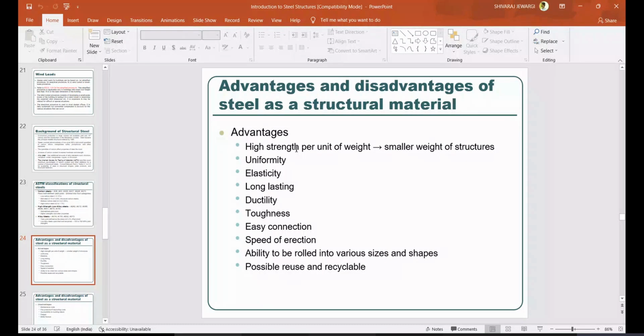Do you know, in the RCC class we have discussed, if you do not use any rebar or reinforcement in a concrete structure, what happens if load is applied on a particular member? Since it is made up of only concrete, it is brittle in nature, since concrete is good at compression. If that member is subjected to tensile stresses, the material is not able to withstand them, so suddenly it will collapse. In order to prevent that, the reinforcement or rebar is introduced, to resist the tensile stresses, right?